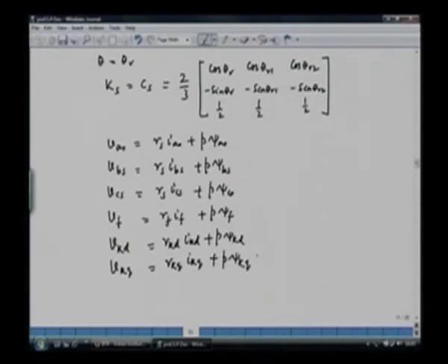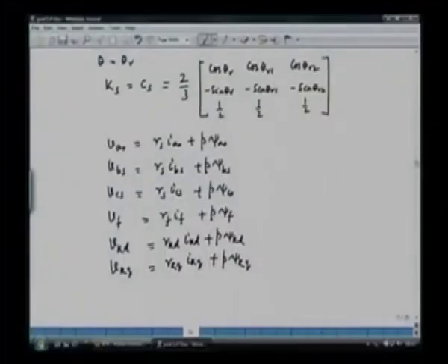Now these equations represent the equation of the actual synchronous machine in 3 phase ABC, and this is a little more involved because we have 1, 2, 3, 4, 5, 6 equations, and we have to solve 6 differential equations, which is more complex. Not only that, the flux linkage here, psi AS, psi BS, psi CS, will involve the inductance matrix and the currents IAS, IBS and ICS, and the inductance matrix will be a function of theta r because of the saliency.